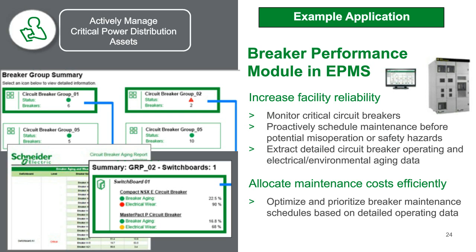A lot of that information is calculated or determined by the status of the breaker, the environmental factors around the breaker, things like the loading of the breaker, every time it was opened and closed, how much did that contact wear down? In the old days, you had to open up a breaker and physically measure the contact to see how much wear there was. Today, you have a way of measuring that from software. So going in and seeing how many times that breaker opened and closed, how much wear there was based on all the external factors on that breaker. What was the loading when that thing opened and closed, and how much wear did that create?